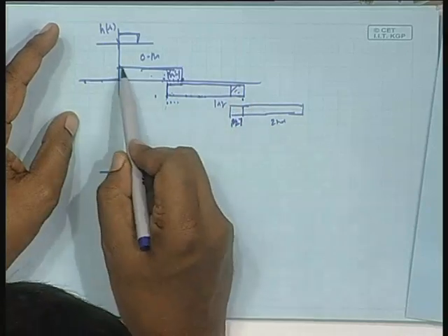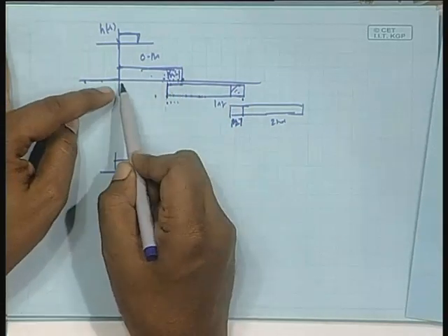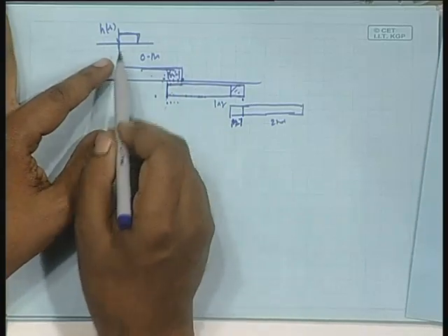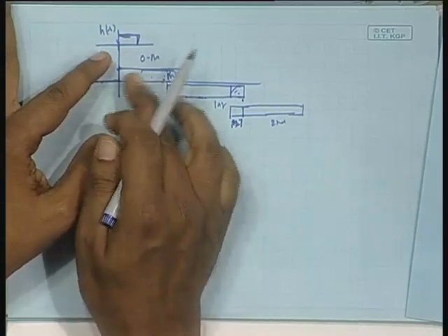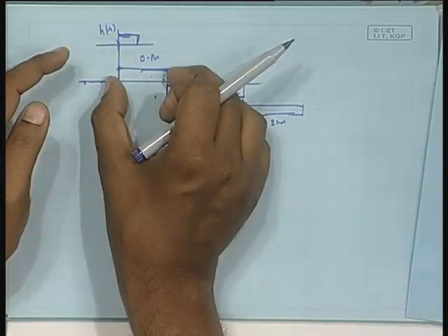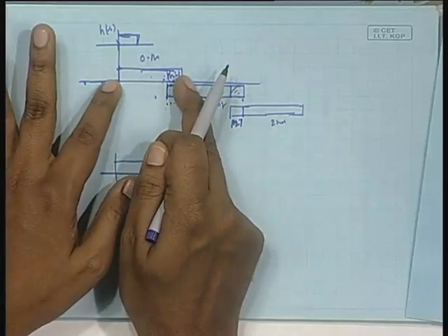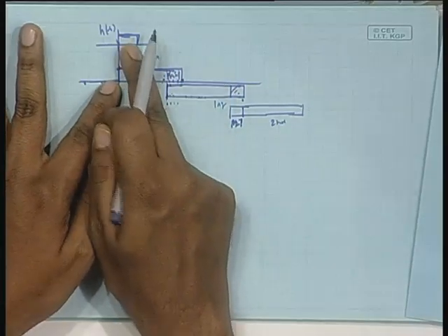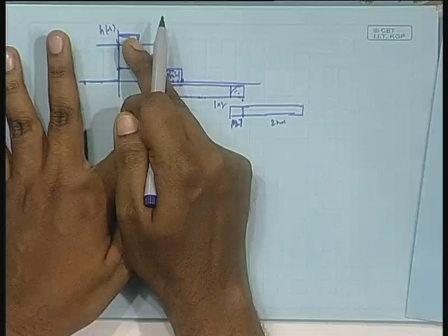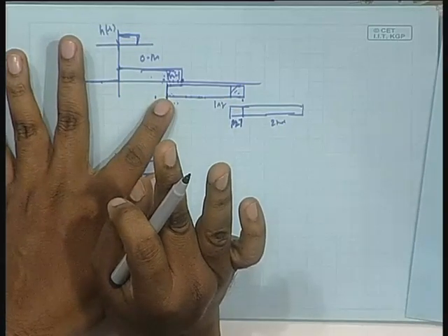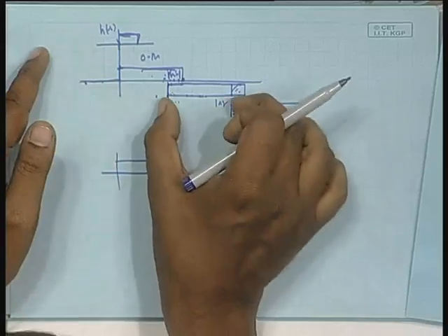Okay. So, this will be my block-adaptive filter; this was the 0th block, with one filter weight. It is slightly different from this context, because I am keeping the filter the same here, convolving always with this guy, whether this block or this block or this block. In the case of the adaptive filter, when I convolve with the filter I have one set of filter weights. When I go to the next block the weight values have changed, but the weight values really are of no concern to me. So their blocks will be overlapping like this.